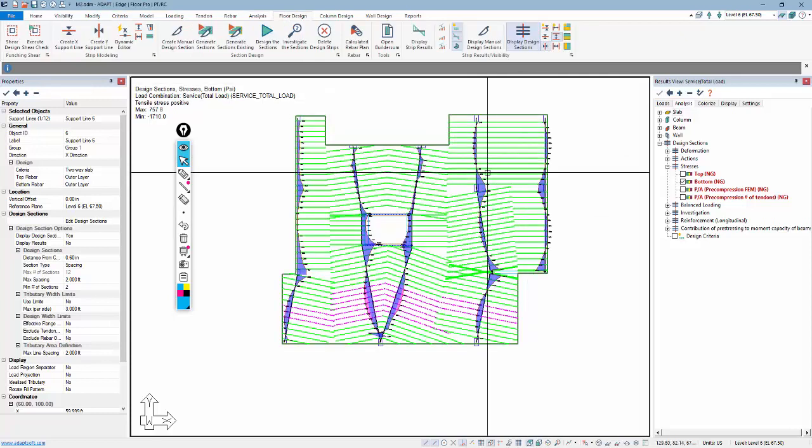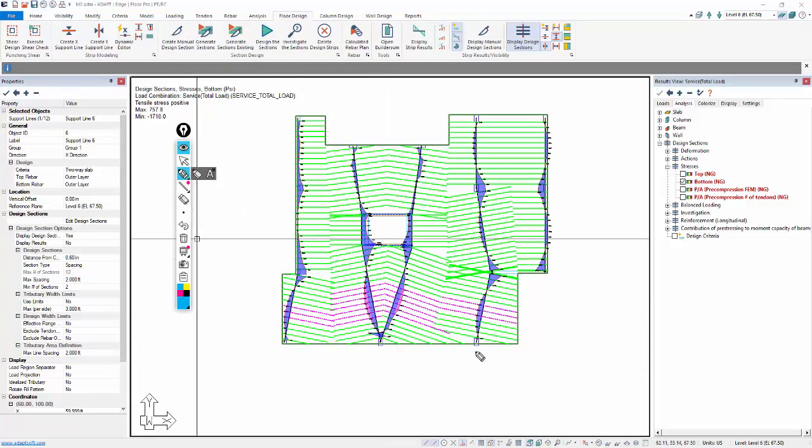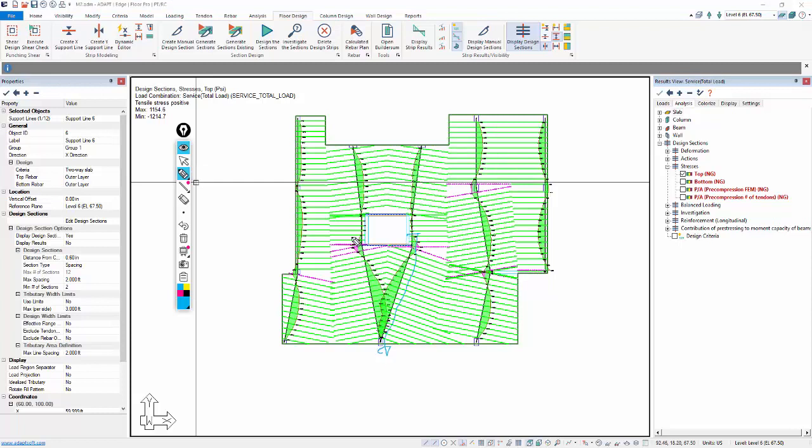In other regions, and here I'm just assuming that the pre-compression is working. If I go over to the Y direction, we have several regions here that don't work. So again, this may be a case because everything's kind of happening down here on the bottom end. I would want to switch over and look at my top stress. You can see there's an exceedance here, there, and then here at the core wall where the tendons are kind of coming off of that corner, we have high negative moment. So in this case, we may want to add tendons here that are anchored back behind this wall, maybe even here also. In this case, we have issues with overstress at supports on the two interior supports. So here, and then we have issues down here for bottom stress. Here we may actually just increase the number of bands through all three spans. So you want to make sure you look at both conditions and determine what might be the best solution for that condition.